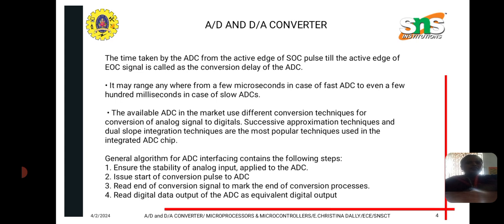The time taken by the ADC from an active edge of the SOC pulse till the active edge of the EOC signal is termed the conversion delay of the ADC. It may range from microseconds in the case of fast ADCs to even a few hundred milliseconds in the case of slow ADCs.